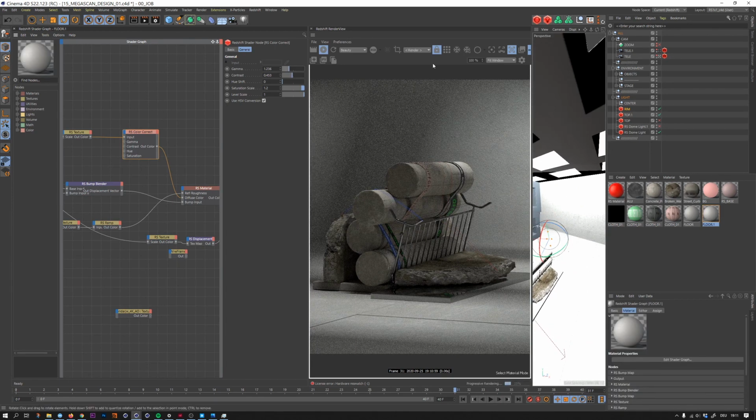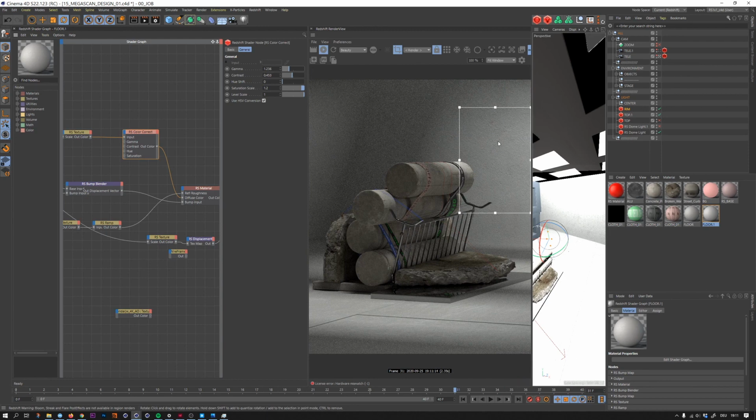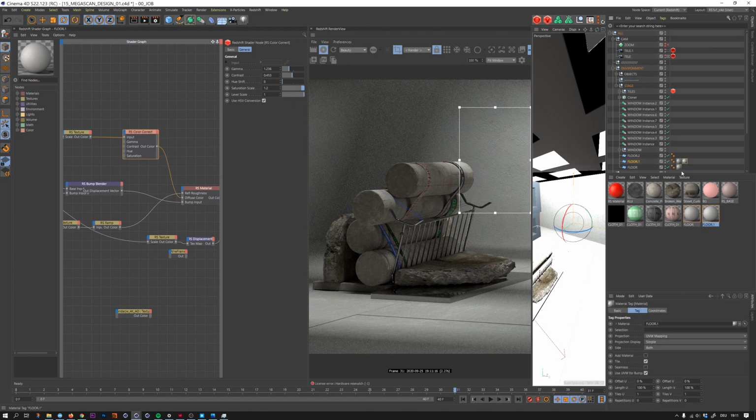And you can see now here, if I, for example, render in this region, that we are back on UV and the scale is really huge. But I think it's nice to see some imperfections on the back, but that's too much. So let's scale the material down a little bit. Oops, I scaled it up. Something like 70 is a good value in here.